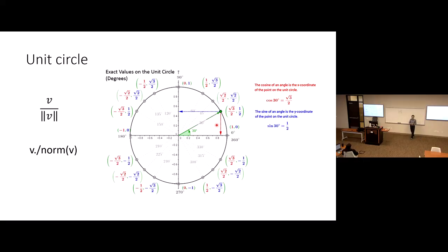In MATLAB, the dot is to indicate this operation is element-based. So if you do dot multiplication or dot division, then each element in there will be divided by this value. In this case, it doesn't matter, because if you ignore the dot, you still divide by a single number. So the operation will be the same.